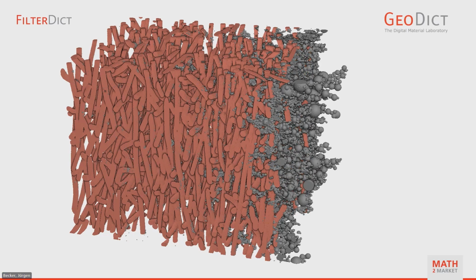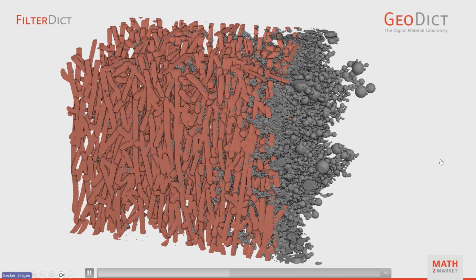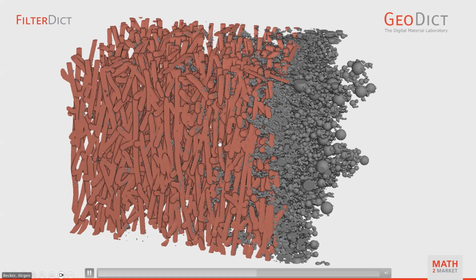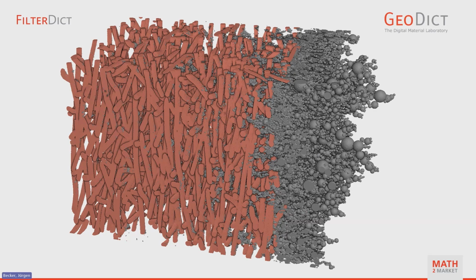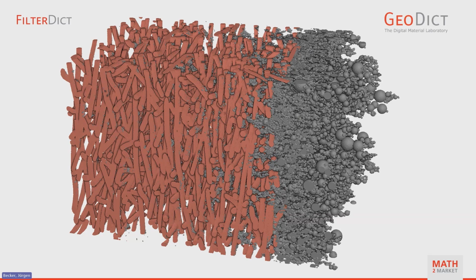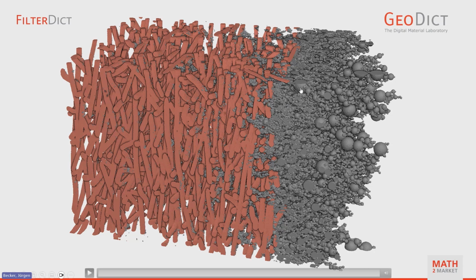In this case, particles come from the right-hand side and move through the filter or are deposited on it. And here we have selected another test dust. So this is one of the standard test dusts, not the small particles that were used for the measurements with the potassium chloride, where the largest particles were about 1 micron. You can see here that the particles are a lot bigger in that case. This is usually done for the lifetime tests.